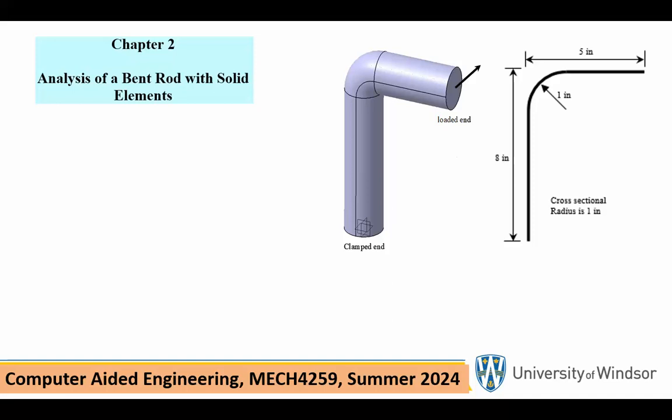And you created a geometry like that, and then the bottom of it is clamped, and a load is into the page at this point. Now, this vertical piece goes through both bending and torsion, and this horizontal piece goes only through bending type deformation. This is how you did this problem in your third year stress analysis class.